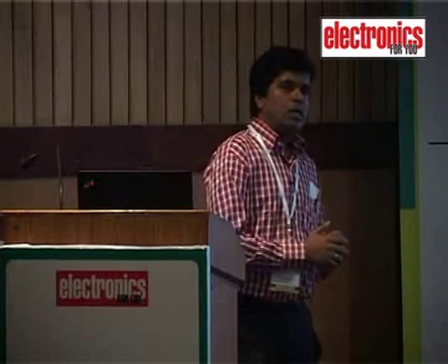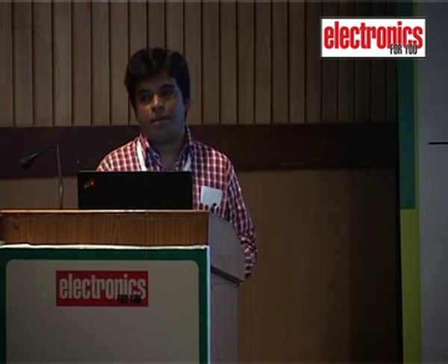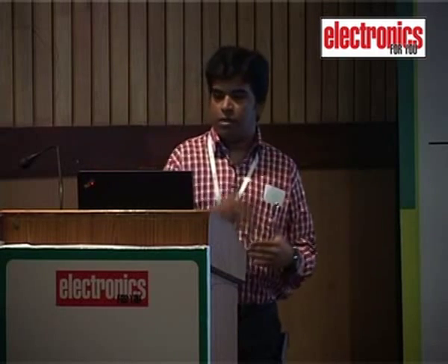Going ahead, what goals we really need to be focusing on for this kind of solution is, well, we have to have some methodology where any image, any picture is translated into a two-dimensional matrix as a ROM, as a read-only memory. That's how we are going to reuse it in our VHDL and Verilog simulation and synthesis as well.